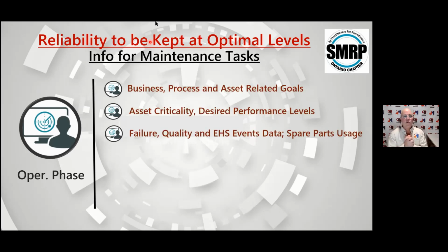Data. We have to rely more on data when we make decisions. So what kind of data? Failure event data. That's very important. Reliability analysis is all about analyzing data, failure data. So MTBF, if you say that reliability is related to MTBF, MTBF means mean time between failures. So we are analyzing failure somehow. So we need to understand data from all of these sources that I present here.